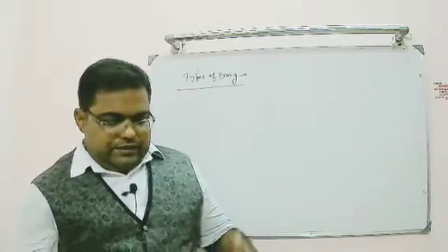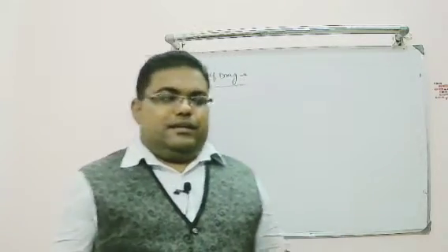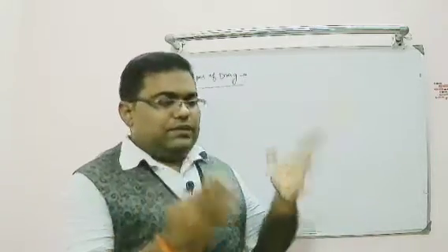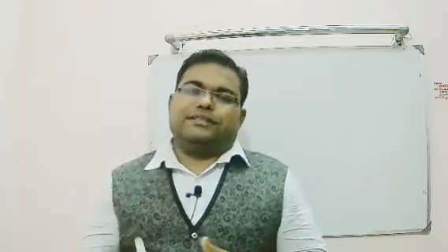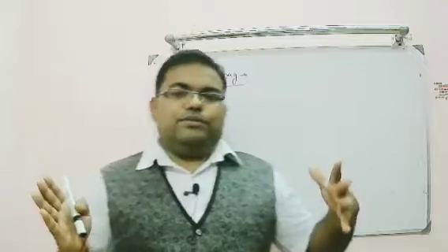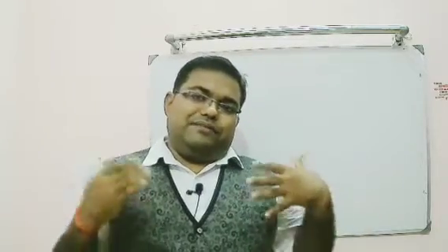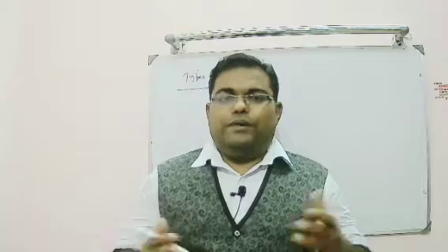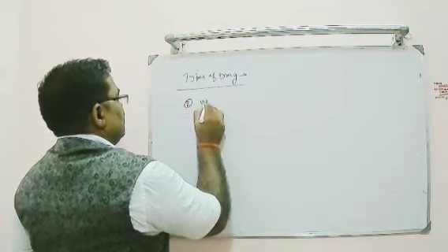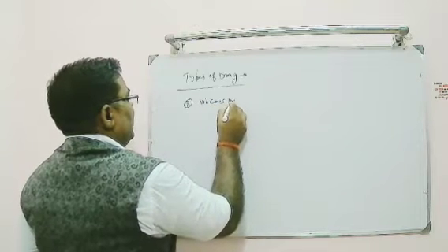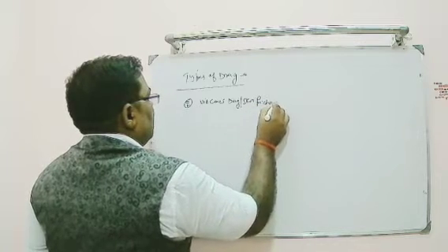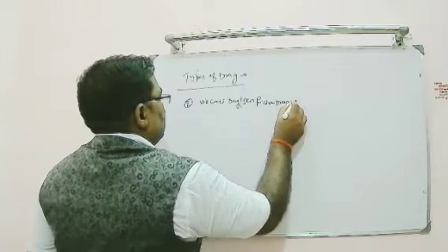So basically total drag has two contributions. First is pressure drag, another is skin friction drag. Skin friction drag is very small, sometimes we neglect it, so the majority of the contribution is from pressure drag. Pressure drag has different kinds of forms, and we will discuss them one by one. Take the first case of drag, that is called viscous drag or skin friction drag. This is a very common drag.